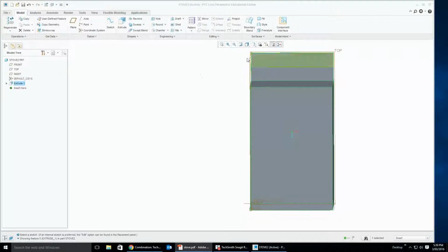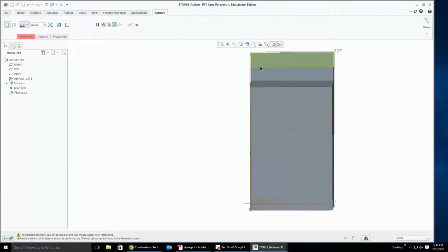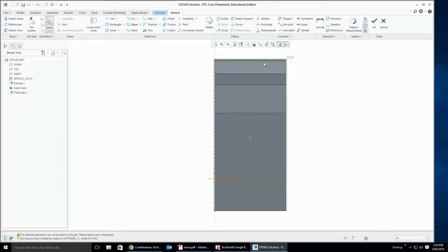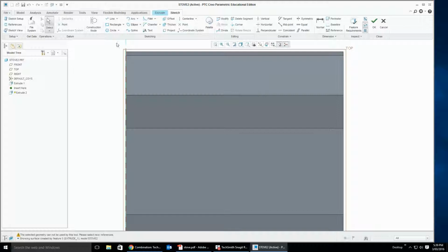So we're going to go up the top here to extrude. We want to extrude onto that surface, so it should highlight green. Once it's highlighted green, click on that. It'll reposition. Zoom in a little bit by scrolling in, and we want to draw 5 circles, roughly. We'll go in the middle just for ease of use here, so roughly there. Draw it out, click once, click again, line them up, click, drag it out so the R's match up, and repeating. So it should lock into that center point, drag it out, and our 5th one, click and drag out. And we're done. Back to our select tool.